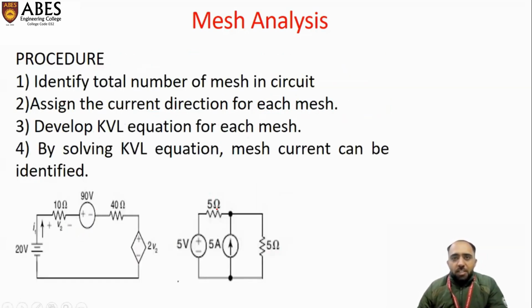Now, how to solve any circuit using mesh analysis? Let's talk about the procedure. First point, identify the total number of mesh in the circuit. First of all, we need to count the total number of mesh in the circuit. If I talk about this circuit, only one mesh is there. So you have to count the total number of mesh.